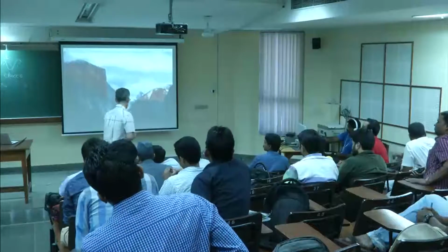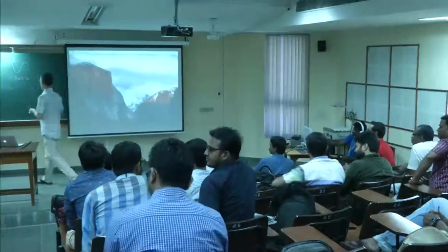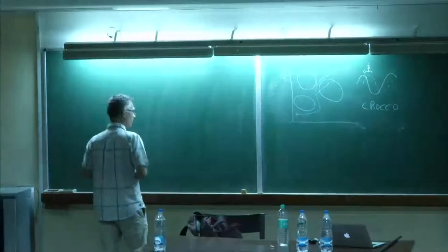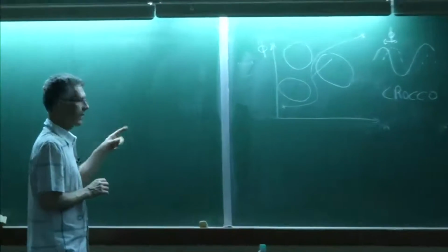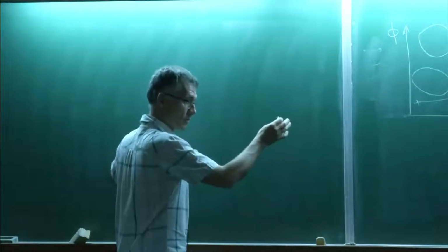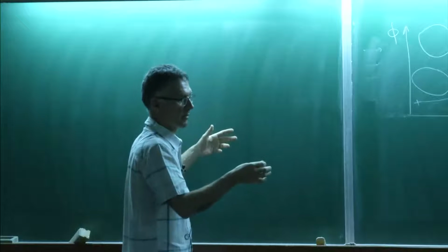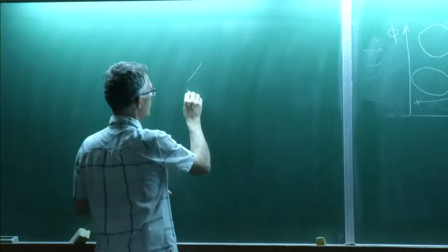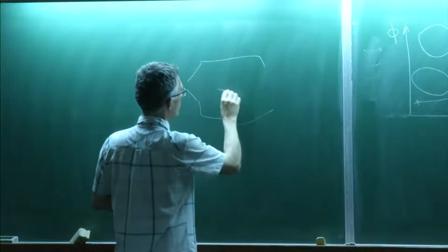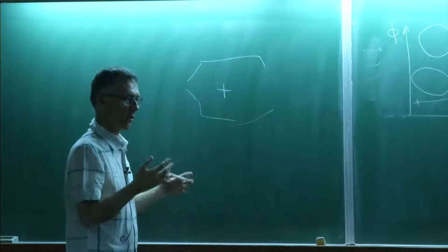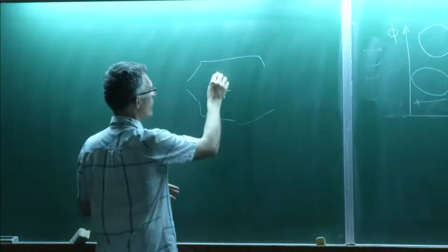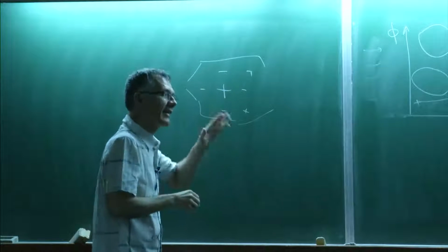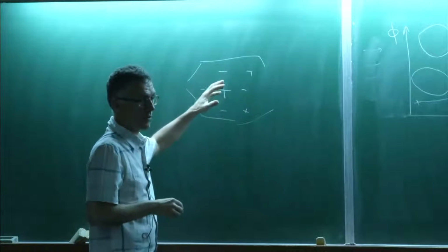Okay, I'm going to do it in 10 minutes, but it's local, and at every point in the flow, you have one Rayleigh criterion, and then you have to integrate over the whole domain, and you have to integrate over time. And the Rayleigh criterion in most flames is not like you have a big plus here. In most cases, when you compute the Rayleigh criterion, you're going to find plus, minus, plus, minus, minus, plus, plus, plus. And the integral is going to be slightly positive. But there are zones which damp the flame and zones which push it.